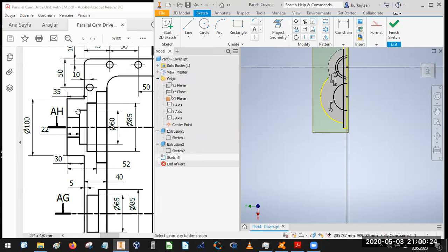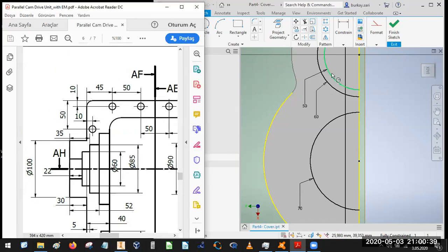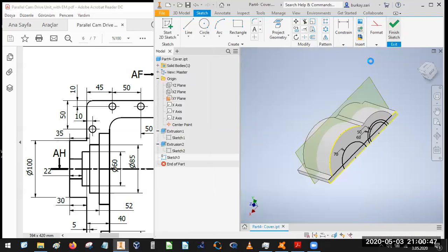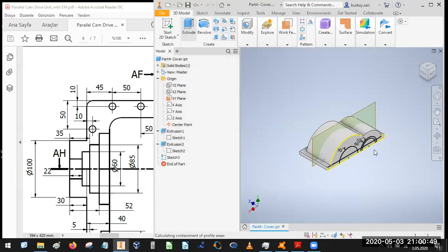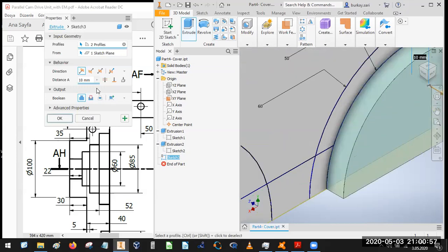Awesome. Here, what I'm going to do is, I will have this 100 or 50 thickness starting from this 180, and after to 140, I will make the first extrusion with 30, then another 30 to make this one to be extruded with 60 millimeter. Okay, I have this extension and that extension, backside, and to be extruded with 60 millimeter.